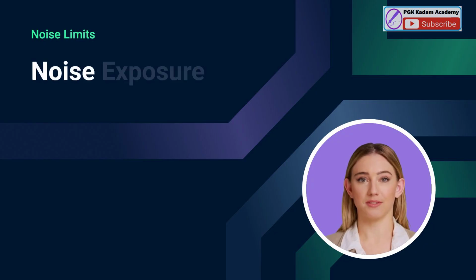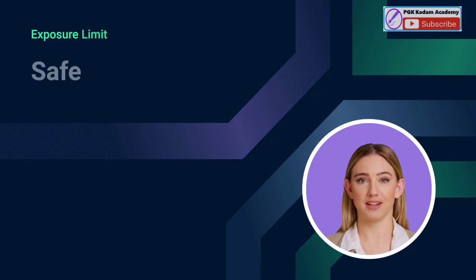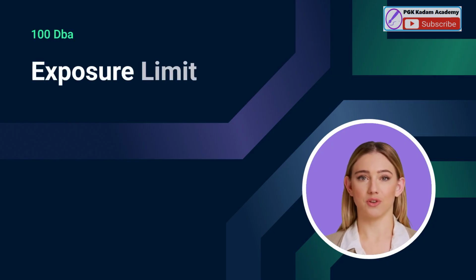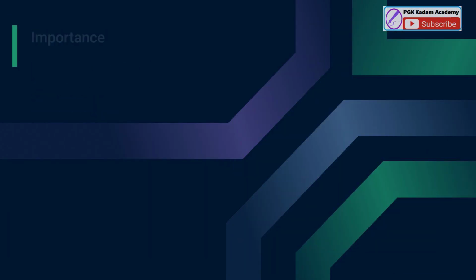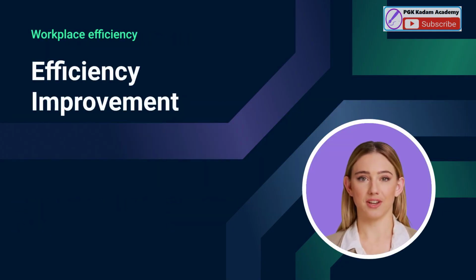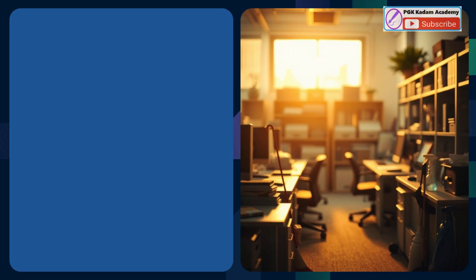Noise exposure limits. Safe exposure limit: below 90 dBA, 8 hours of exposure is safe. Limited exposure: it is unsafe to be exposed to 100 dBA for more than 1 hour. Organization of work materials. Designated storage. A suitable place should be provided for everything connected with the job. This principle of a place for everything and everything in its place improves efficiency and reduces time wasted searching for tools or materials.